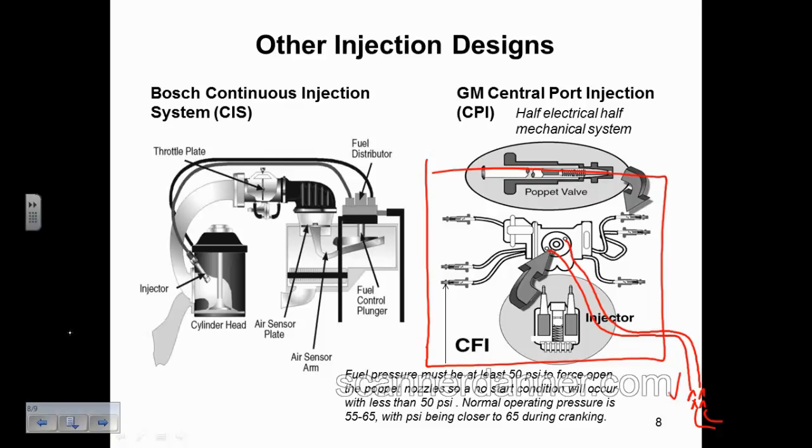Yeah, and I didn't bother to look up a spec. I had spark, I had injection pulse, I had fuel pressure. I could not get this vehicle to run. I am not exaggerating, guys. I had about 6 hours on this truck, going after compression. If you know the 4.3, doing a compression test on the 4.3 is about a 2-hour process alone. And then checking for exhaust restrictions, and I don't even know where my head was. It was so long ago.